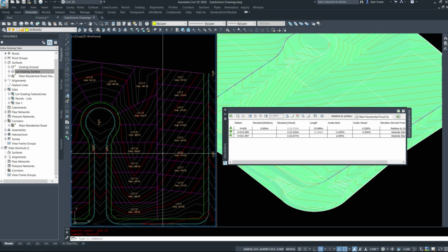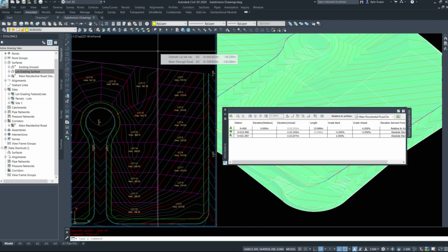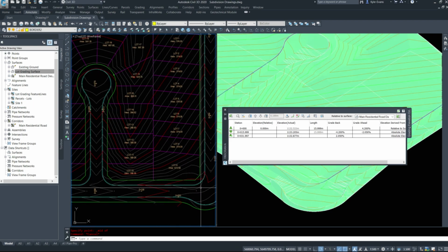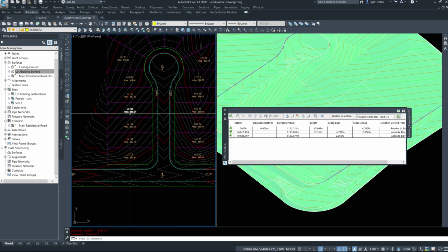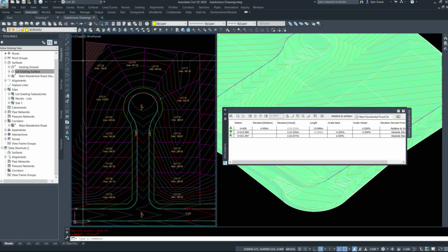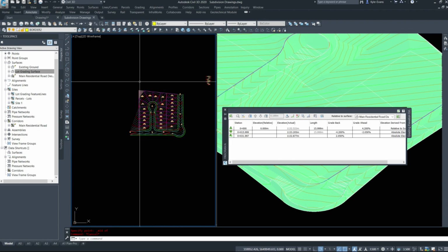So there will have to be a back swale behind these lots, which is just a concrete trough for water, because half the lots are flowing out there and the swale will drain to the road and probably down to our low point here. The rest of the lots I've just graded up at 2%. We don't know what is around here. However, in a larger subdivision, we would have to tie this in together everywhere.